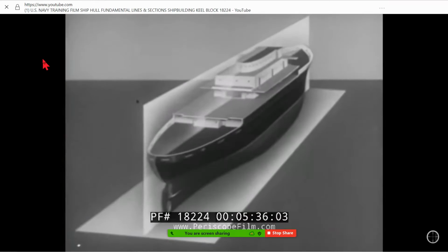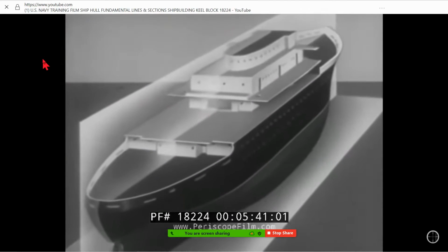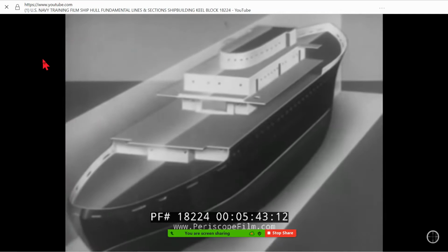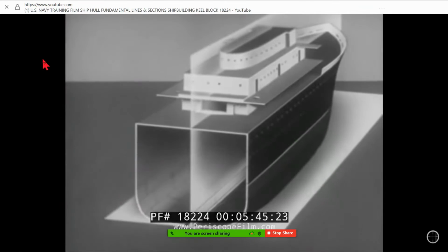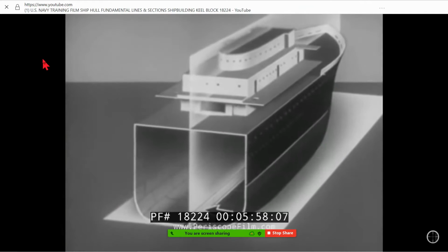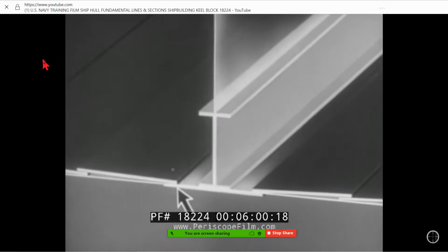Perhaps the quickest way to gain a working knowledge of ship's terms and symbols is to study the ship's structure. At the very base of the ship, where the base line and the center line intersect, two long steel members provide the backbone of the ship. This flat steel member, usually so placed that its upper surface touches the baseline, is known as the flat keel. Its symbol is K.